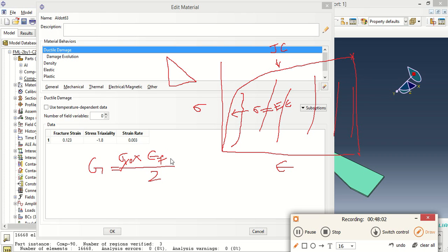So usually a parameter called characteristic element length is included to know, with respect to the mesh, when the damage is going to initiate and in which direction. So the mesh or element size involvement is very important here. What is your element size? Multiplying this by this will increase the fracture energy. So your fracture energy is increased and your result becomes more and more accurate.